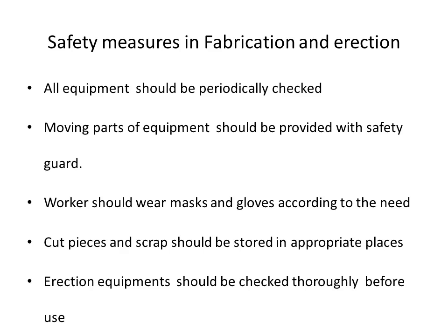So while fabricating, we will be using different types of equipment like gas cutting equipment, welding equipment, drills, etc. All these equipment should be periodically checked, and the moving parts of these equipment should be provided with a safety guard. The workers engaging in such types of work like welding, cutting, etc. should ensure that they are wearing a mask as well as safety gloves to ensure their personal safety.